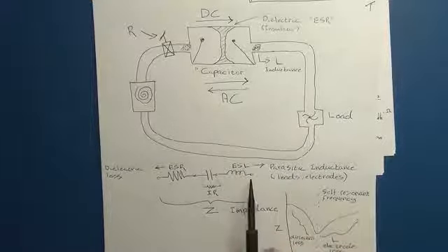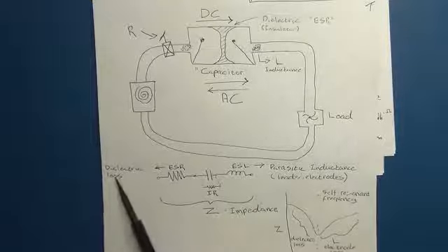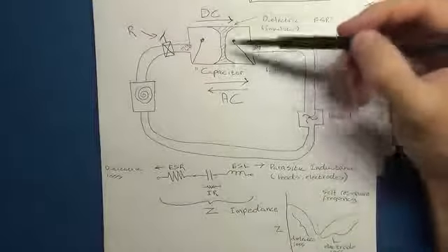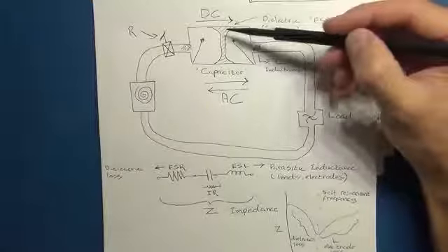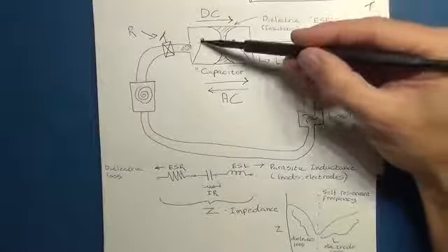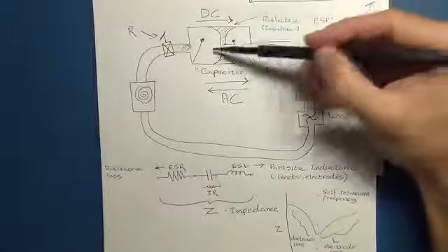Now, the ESR can be seen as the dielectric loss. If we have a look at our little analogy over here, these bellows, the space in between the bellows, which is acting as our dielectric if you like, that movement or restriction on the flow of current is obviously going to have an effect on the loss of a capacitor, and that accounts for the ESR. The steel wool over here would be like the inductance. That acts as the inductance.